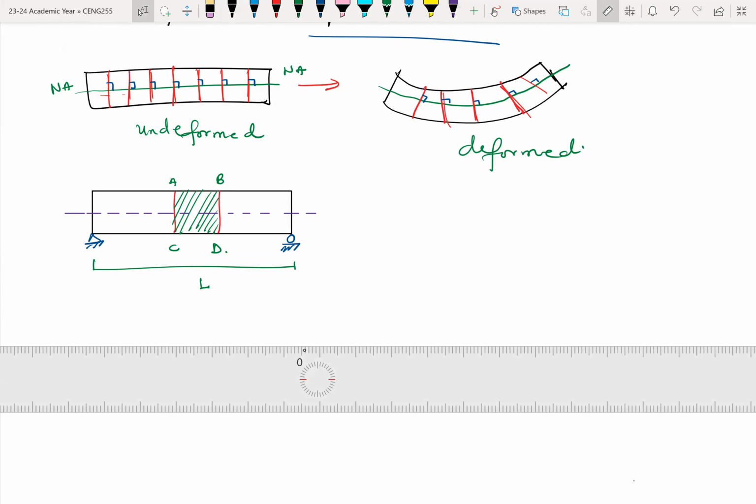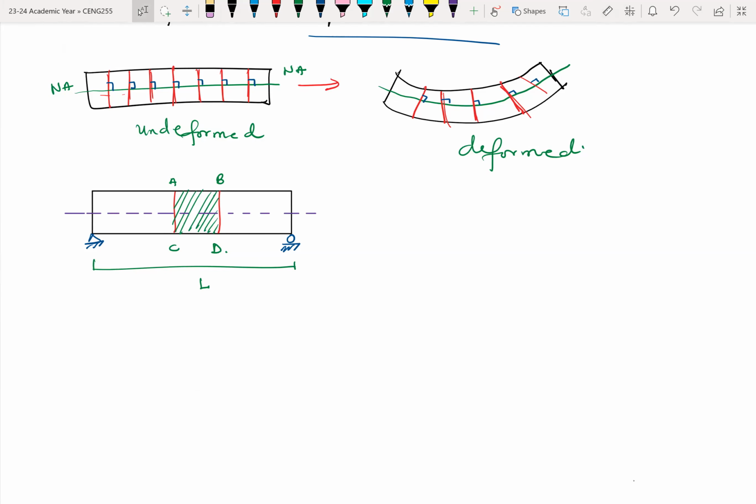So this is a neutral axis. The neutral axis simply means that it is a position along which, when your beam deforms, that part of the beam doesn't have any change, or there's no change in the length of the beam during deformation. Okay. Things will come full circle very soon. Again, if at some point you don't get anything, you can just let me know.